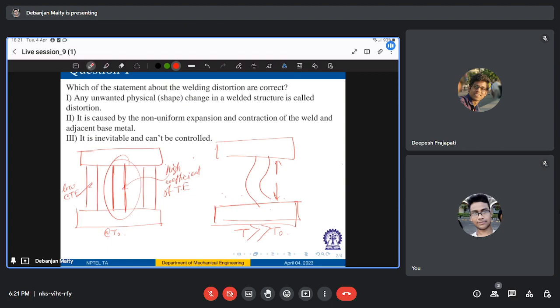So when stresses can cause this macroscopic distortion, they will do so, right? And in the process of causing this distortion, whatever thermally induced stresses were there during the process will be relieved, at least to below the yield stress, and possibly to some lower levels.